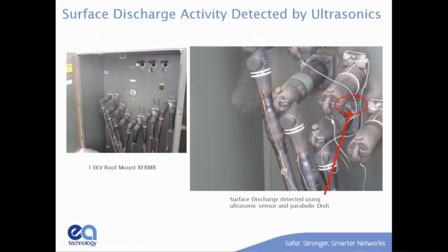Here's an example. I did this myself. This is on the roof of a freeze-dried food building where they require factory guys to come do a test. And every year we come and do a cable test on all the 13 kV cables. I went up to this cabinet, and it's dead front. It's safe to open the door. I'm a bit of a chicken, though, so I do an ultrasonic test around each door and a TEV test on the door before I open it because I'm worried about personal safety.